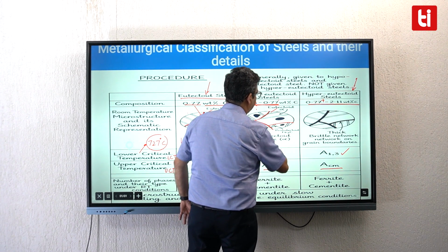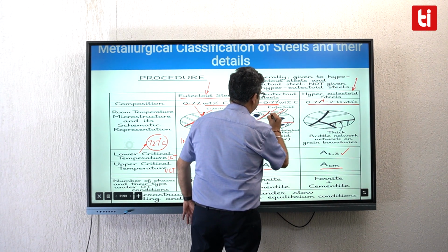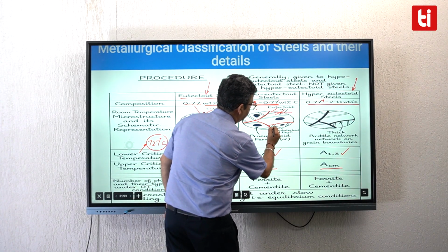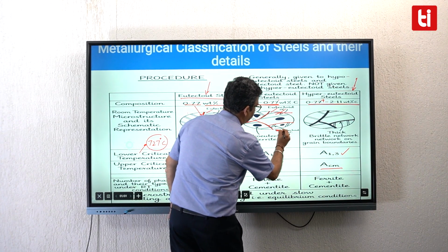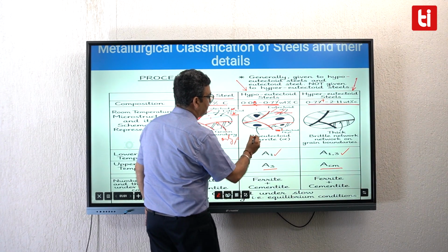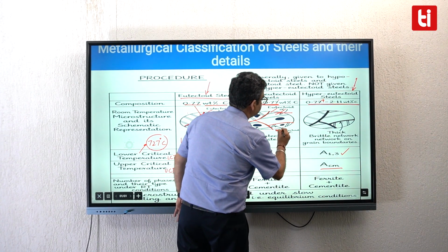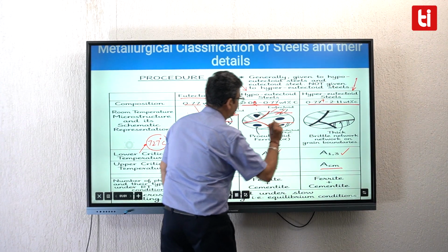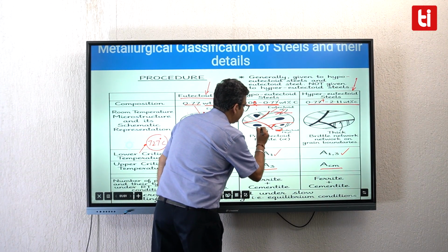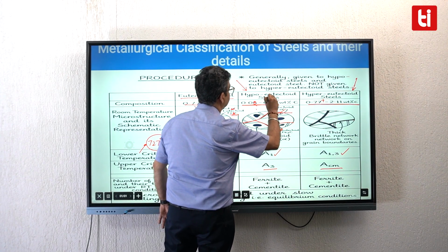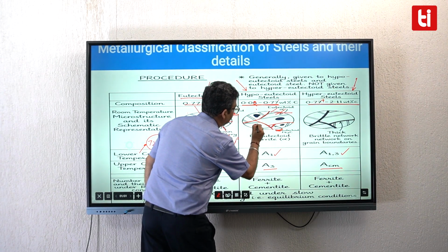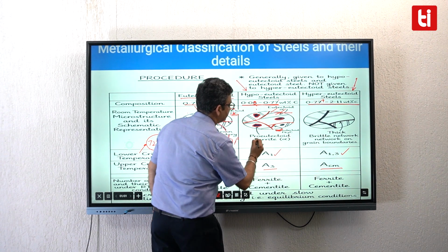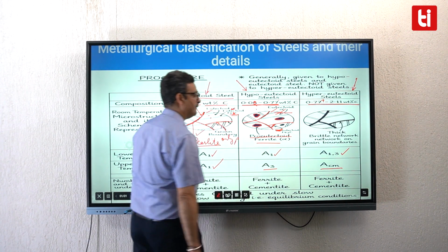This again is eutectoid ferrite. The thinner lamella is eutectoid cementite. So this thinner lamella is eutectoid cementite. And this pro-eutectoid constituent in the case of hypoeutectoid steels is ferrite. This ferrite that is sitting within the grains in the form of lumps is pro-eutectoid ferrite.